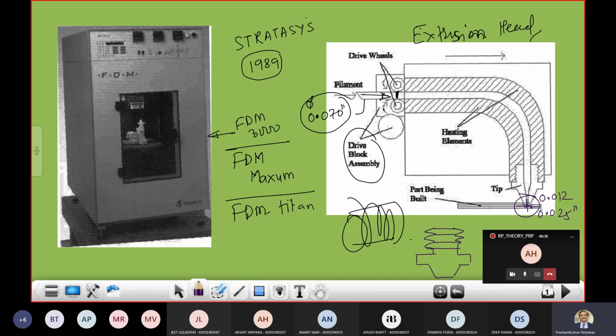Usually it is suggested that a designer add some alignment bosses or slots, so that proper alignment of the subsections can be easily achieved with the help of this system.